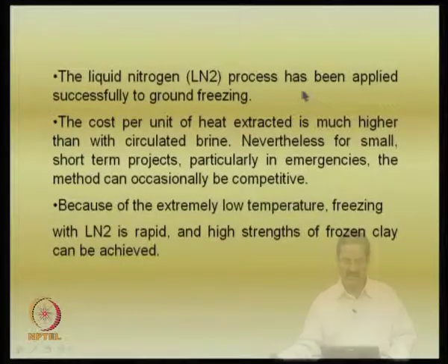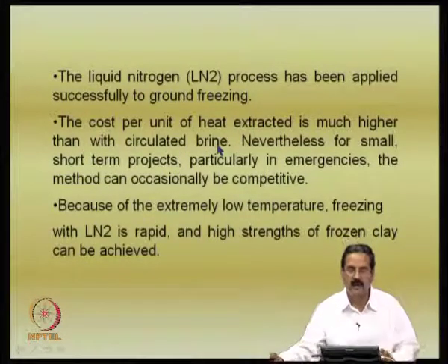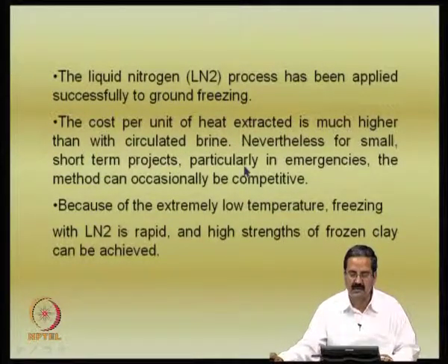The liquid nitrogen process has been applied successfully to ground freezing in some places, and the cost per unit of heat extracted is much higher than with circulated brine. The brine solution is somewhat cheaper compared to liquid nitrogen. Nevertheless, for small short term projects, particularly in emergencies, the method can occasionally be competitive. Because of the extremely low temperature, freezing with LN2 is rapid and high strengths of frozen clay can be achieved.